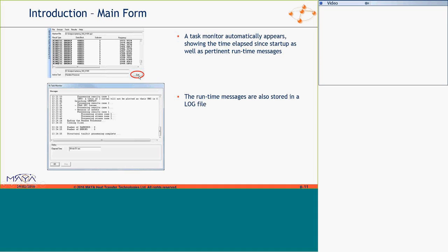And there's a very small start button on the bottom right. Once you've picked your OP2 file, you've imported your groups, you've clicked on tools, and you've defined the contents of your processor and your options, then you click the start button. Then we actually launch the executable for the core code, the processor.